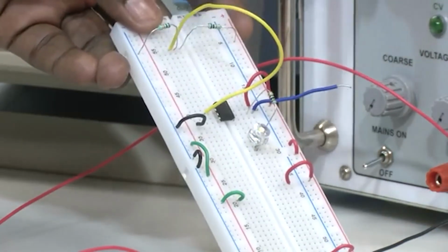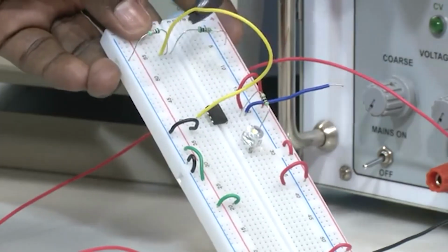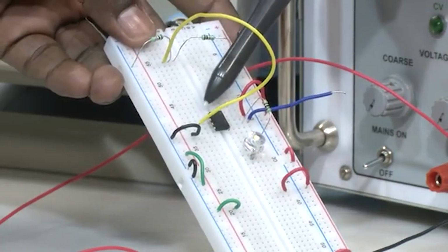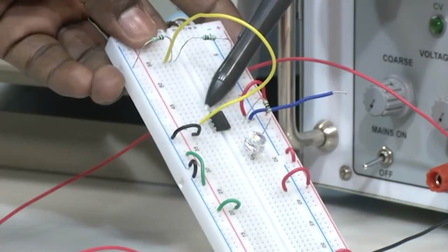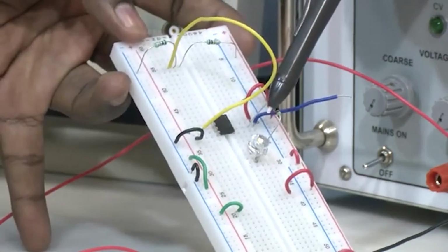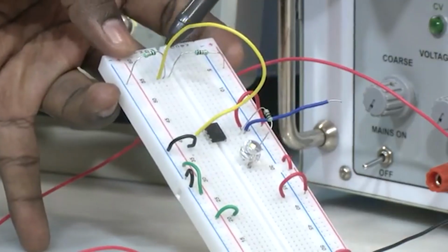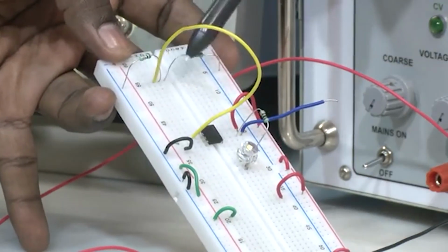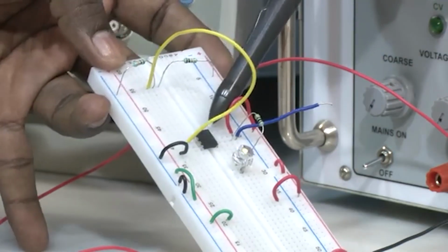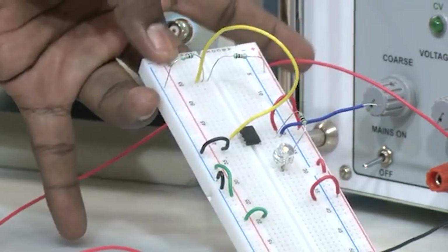through the potentiometer or through the potential divider, the two resistors, we are applying voltage V reference to the one terminal which is inverting terminal of the operational amplifier, right. So, understand again, output is connected through limiting resistor to the LED, input inverting terminal connected through potential divider to the op amp inverting input. Non inverting input we will apply using the potentiometer or using the power supply.